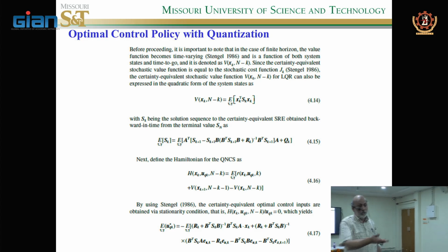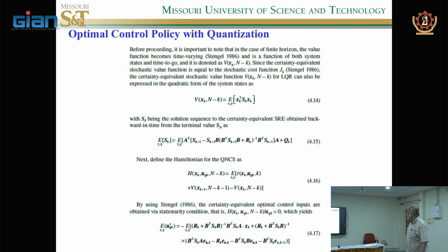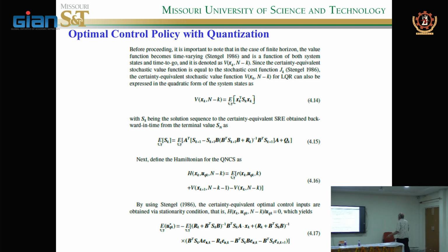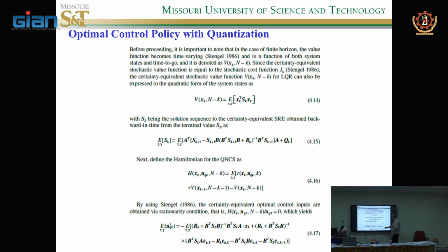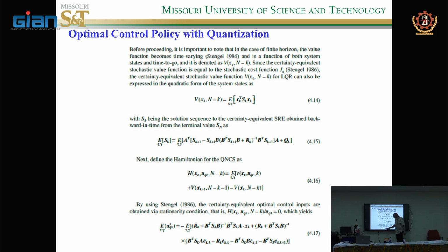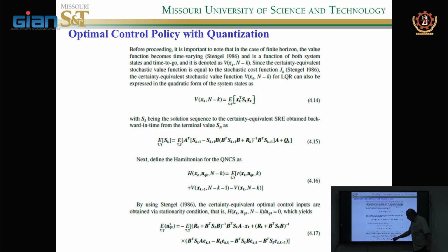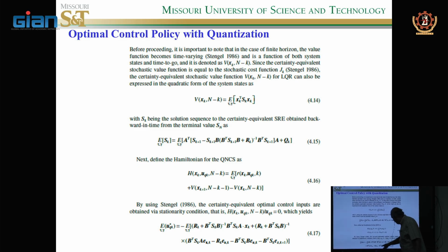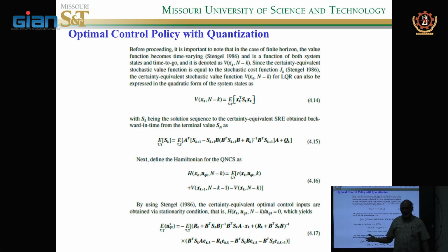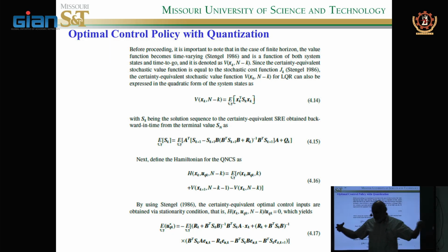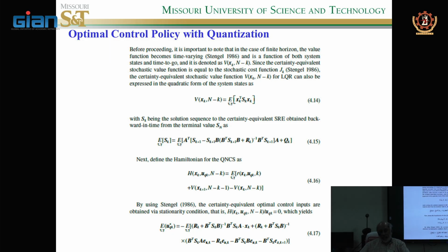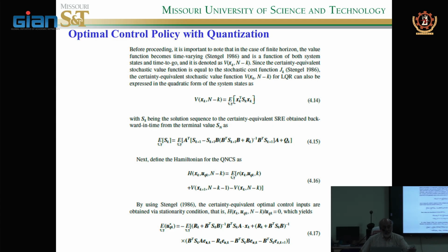No, selection, you select. Okay, but what equation 4.17 says is, if you have errors both in E due to quantization and in U, those error terms show up, and they get multiplied with all these B and A matrices. So that's how the error becomes significant a lot of times, and it can also cause instability.